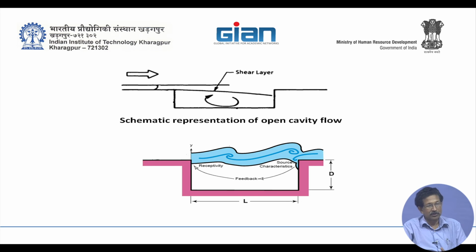There is an oscillation which is sustained by itself, and with that this shear layer deflects up and down, giving rise to an unsteady flow, which in the literature is often referred to as mass addition, mass removal. Some of the mass from the outside flow is captured by this shear layer, and in the next half of the cycle it is again removed, expelled.